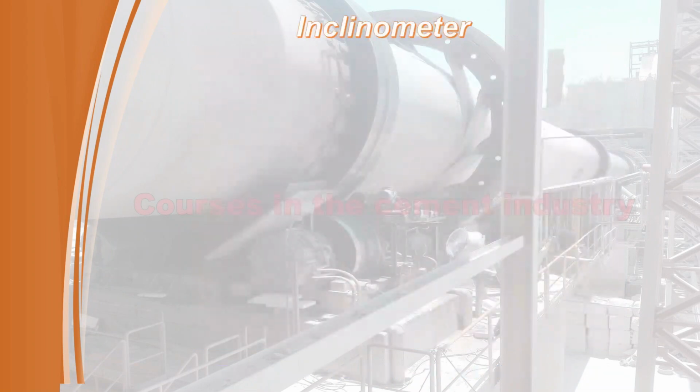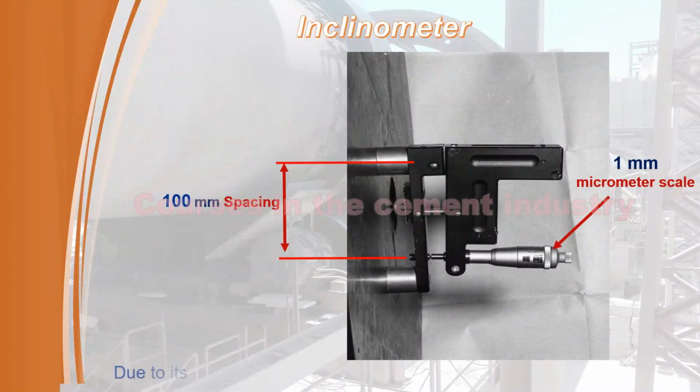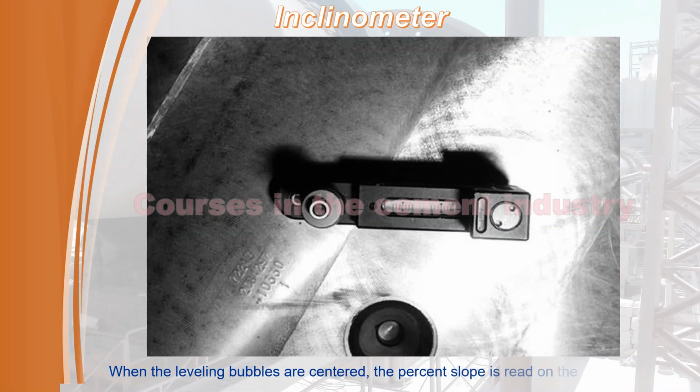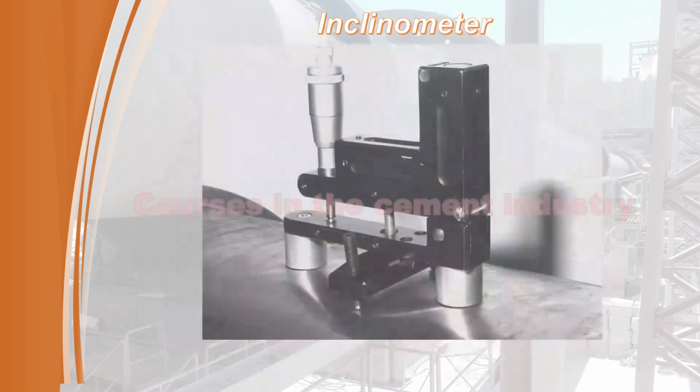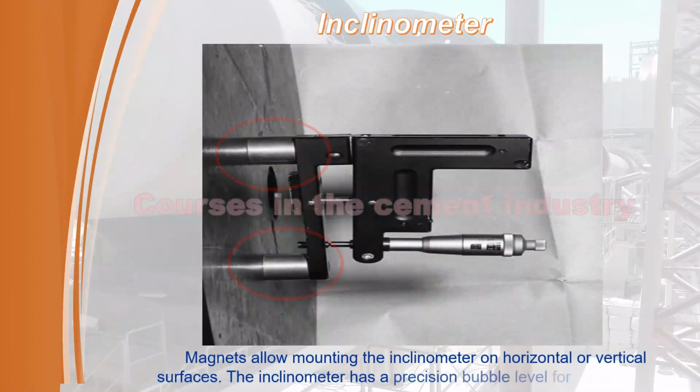Inclinometer, to measure roller slope. See in the figure. Due to its dimensioning, the inclinometer reads the percent slope directly. See in the figure. When the leveling bubbles are centered, the percent slope is read on the micrometer dial. See in the figure. Magnets allow mounting the inclinometer on horizontal or vertical surfaces. The inclinometer has a precision bubble level for each position.